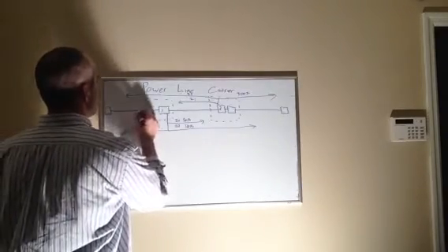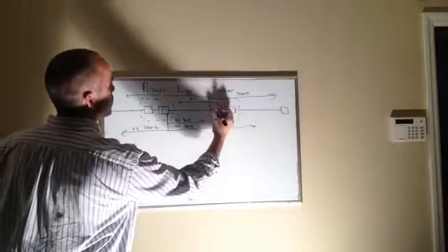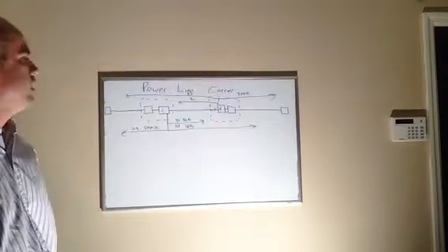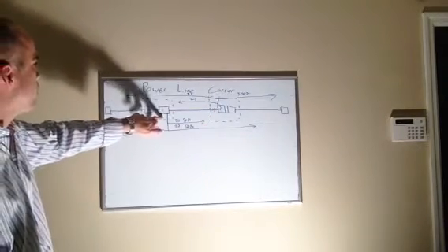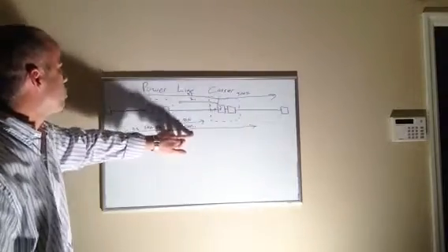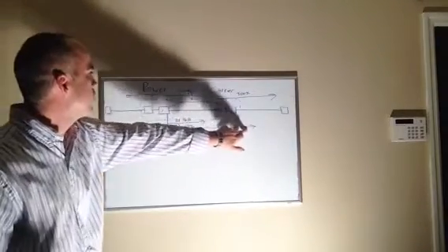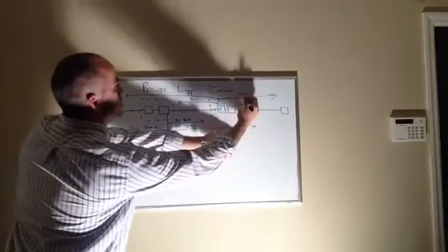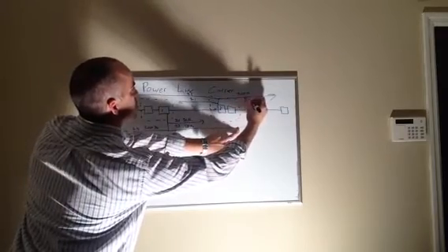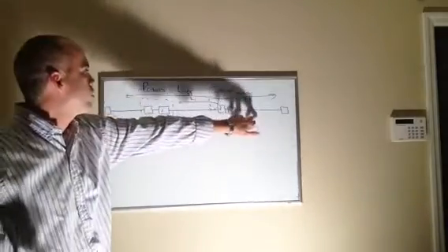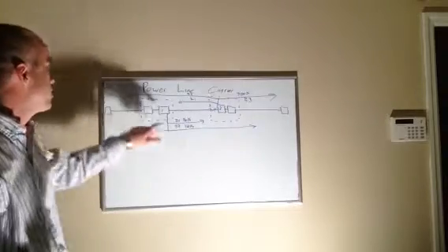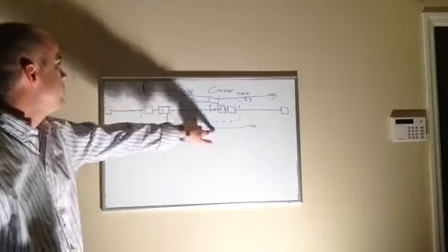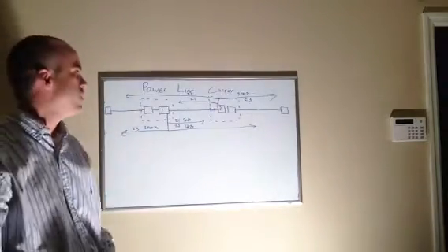So let's go through it one more time. Okay, we'll put the fault here this time. Breaker 2, Zone 1 sees the fault. Instantaneous trip. Breaker 1, Zone 2 sees it. Zone 1 doesn't see it. Zone 2 sees it, forward looking. Zone 3 from breaker 2, this one right here, does not see the fault in the reverse direction, therefore does not send a blocking signal to breaker number 1, and lets breaker number 1 trip Zone 2 instantaneous. No time, no 20 cycles, high speed trip.